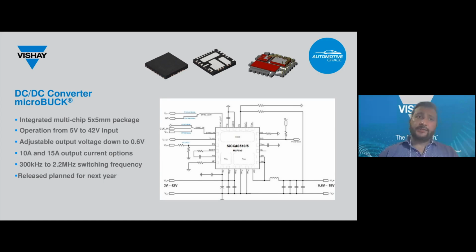So here are more details on the Vishay microbuck that I was mentioning. The part that was used for this design actually has a commercial grade, but the automotive version will be released later this year. It's basically an integrated design with both the control IC and both power MOSFETs in a 5x5 millimeter package. The other components required are a storage inductor and an output capacitor.